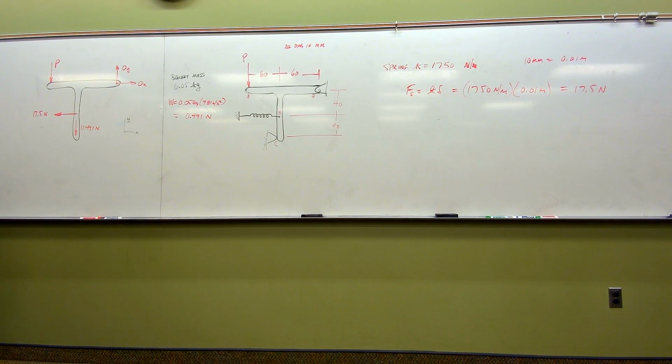Now, in the same vein of the previous problem, if I look at my free body diagram, I have a grand total here of 1, 2, 3 unknowns. That's a known force, that's a known force. 3 unknowns, 3 equations in the budget, but I only need 1. It's the same thing we talked about before, folks. I can figure out what OX and OY are, but I'm not asked to. I don't care.